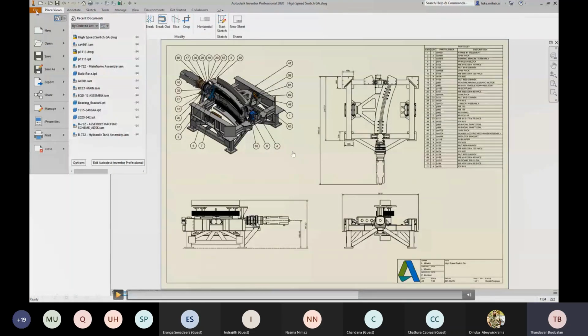Like you would have seen in the video now, where he goes back to AutoCAD and changes the height of the bracket. Then he comes back to Inventor and refreshes the design, so the 3D model also gets refreshed, and the same will be reflected throughout your entire design, even the part assembly and even in the documentation, till the BOQ and part files. Okay, everywhere it will get reflected. So that's the kind of integration available between AutoCAD and Inventor here.